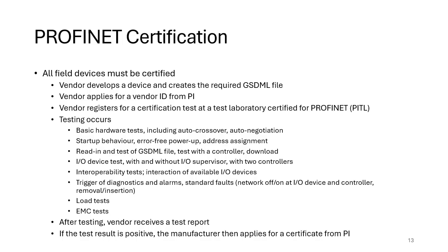The PROFINET testing lab certifies startup behavior, that power up is error-free. They look at address assignment. There would be reading and testing of the GSDML file. Then there would be testing of the controller, downloading of the GSDML configuration from the controller to the I/O device.